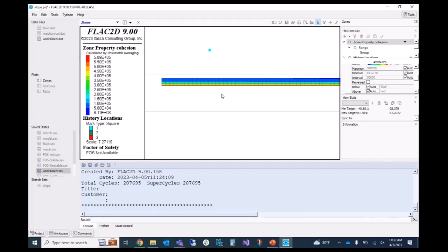What we're going to do is put the slurry wall in. Because what happened in reality was they did the initial model that had that factor of safety of 1.1. They put the slurry wall in, and they got a factor of safety of like 0.99 or something less than 1. And so they said, okay, this is really questionable because we actually did this and it's still standing. So this was really the motivation for doing this.